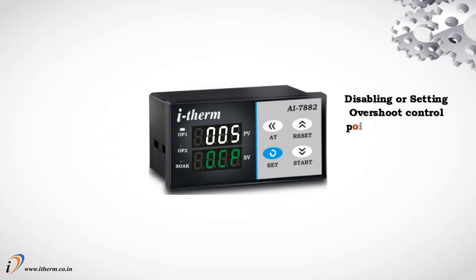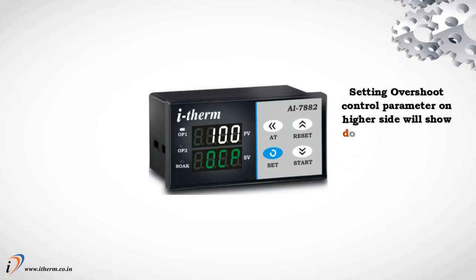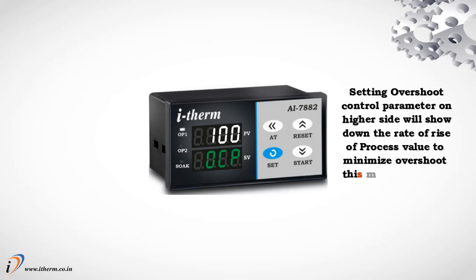Disabling or setting the overshoot control point parameter on the lower side will increase the rate of rise of the process value, which may cause overshoot. Setting the overshoot control parameter on the higher side will slow down the rate of rise of the process value to minimize overshoot. This may cause a delay to reach the set point.